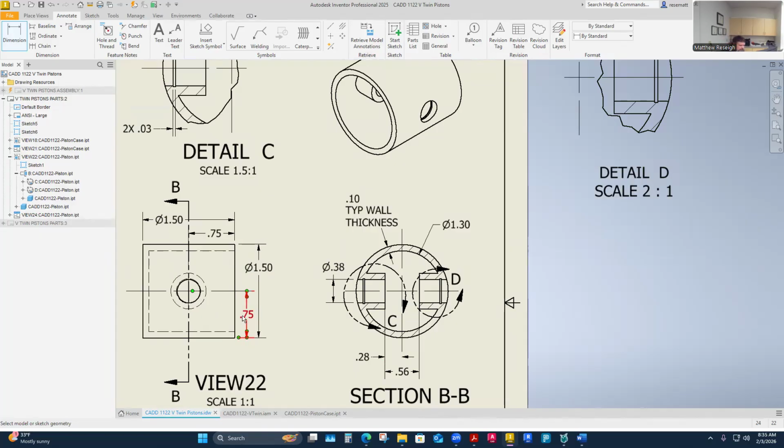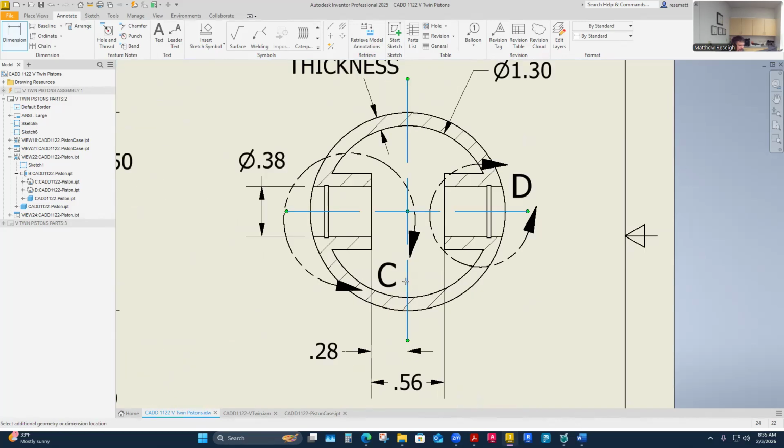You'll see sometimes these dimensions are dropped if it's clearly showed with center lines. Could be the case here. It was always that debatable thing in CAD as well. I know I showed the width. This one I like better to have at least one of those dimensions. I'm coming off center to this side, and then it's 5/6 wide here. So it kind of gives me a center controlled dimension grouping.